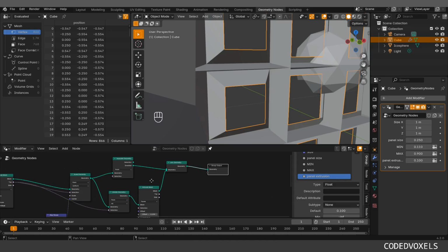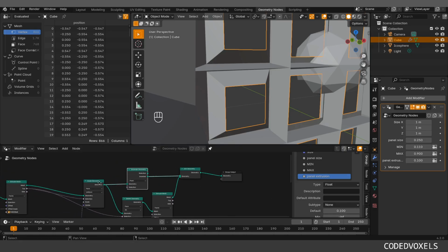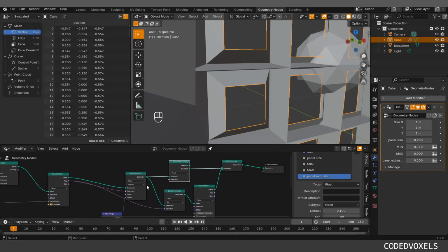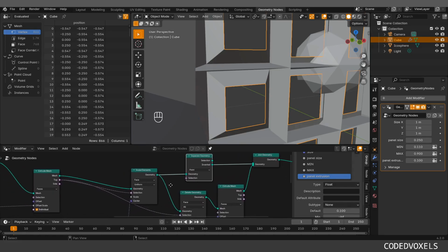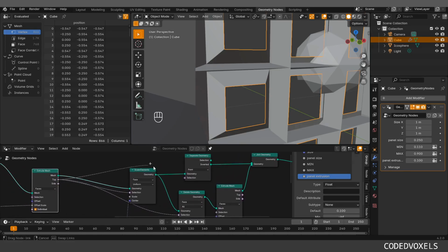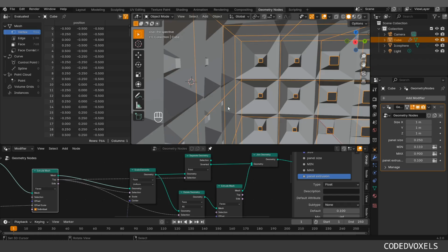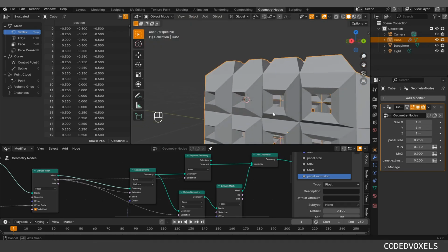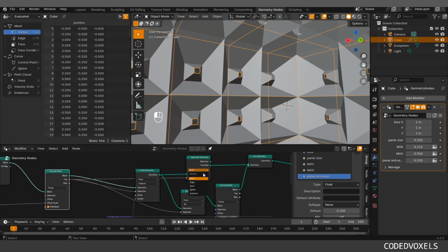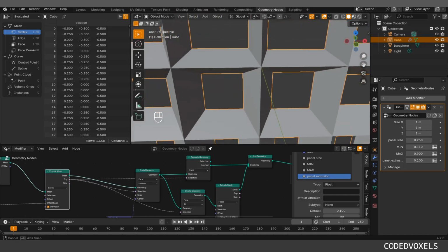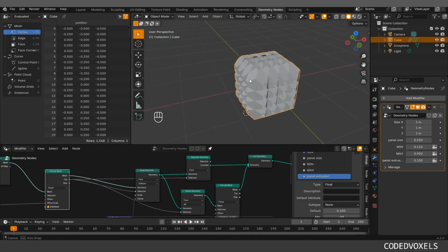Nope. So let me think what's happening here. We have the scale element, then we separate the geometry, and then what we're gonna do is we're gonna add the inverted thing. Oh, I never gave it a selection here in the separate geometry. So we want this top geometry, the same one that we have in the scale element. And now, if everything's correct, it should be there. It looks weird. Not sure what's happening. Oh, not point, face. Sorry, but okay, that's what we want. Good. Looks good from the inside, looks good from the outside.